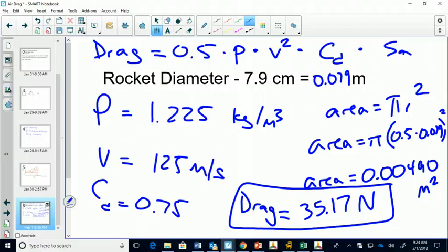Does that make sense, my friends? You said the drag is not really specified unit. No, it's unitless. Okay, so it's not always going to be unit. Sorry, the coefficient of drag, the CD, is always unitless. The drag is always a force. It's always a force. It'll always be, for our purposes, because we're doing SI units, yes, it'll always be in newtons.